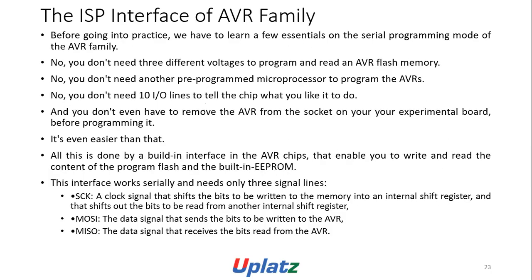The ISP interface of the AVR family. Before we go into practice, we have to learn a few essentials on serial programming mode of the AVR family. No, you don't need 3 different voltages to program and read an AVR flash memory. No, you don't need another pre-programmed microprocessor to program the AVR. No, you don't need 10 I/O lines to tell the chip what you like it to do. And you don't even have to remove the AVR from the socket on your experimental board before programming it. It is even easier than that.